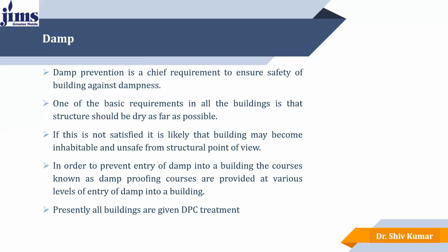In order to prevent entry of damp into a building, courses known as damp proofing courses are provided at various entry levels of the damp, which is commonly known as DPC treatment. The DPC treatment is provided over the foundation at ground level, and after that, the wall is constructed over the DPC. So it checks the soil water from penetrating into the wall.